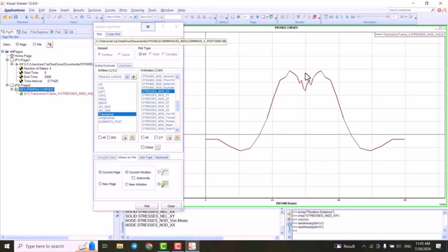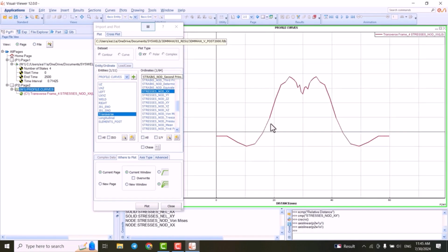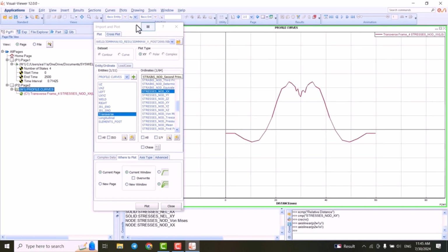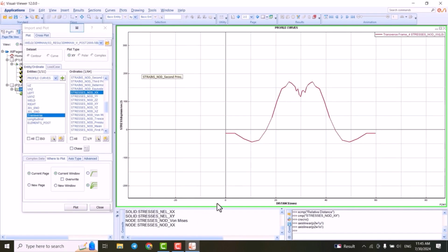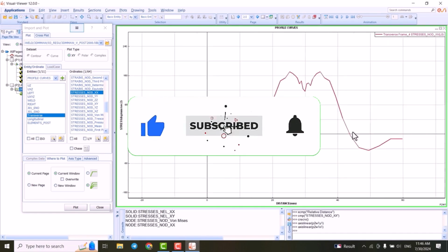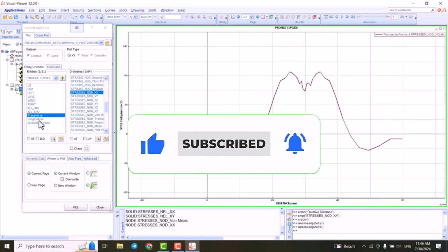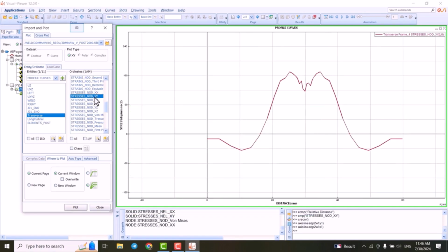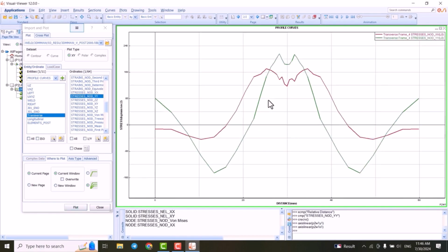If I was on the other line I told you, it might not be like this, but the trend is pretty much the same as what I showed you. In the weld direction we have compressive stresses here, and we have tension stresses here, and it is so high. And what we can do is to plot the stress in YY direction.